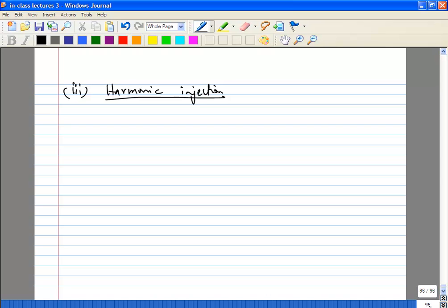Okay, especially the differential voltage is going to have the component which you need, plus maybe the third, fifth and so on. Okay, but each side of the oscillator as well as the common mode nodes are all going to have the even harmonics. Okay, because remember, the oscillator still has some operation in the even harmonic, even though it's undesired. What you see as a voltage will just be the odd harmonic.